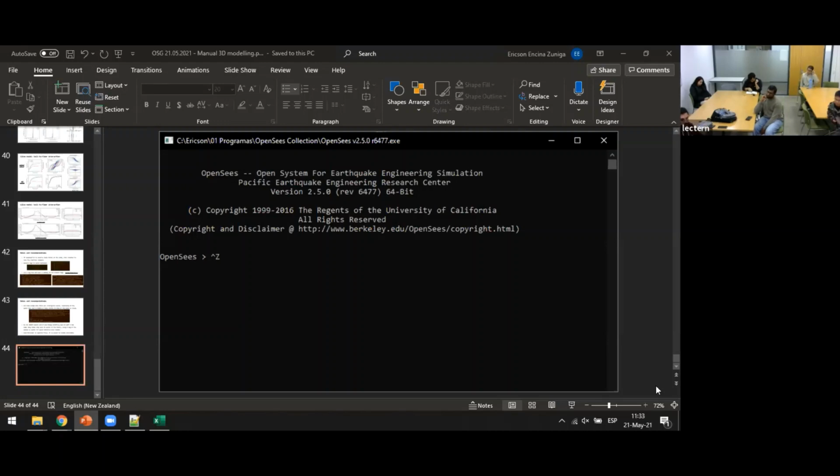It would be really cool if you could have 250 millimeter shells, but the problem is that one model takes 140 hours, as in the examples I put on the screen, so that's really difficult to do. And no one has that much time. So you select different shell sizes for whatever you need, run the analysis, and see how your structure behaves and how much it changed.